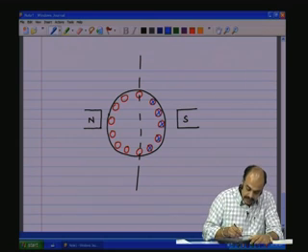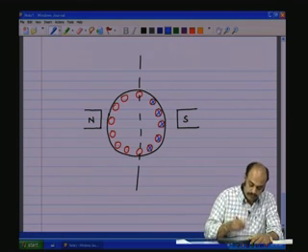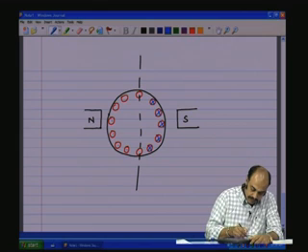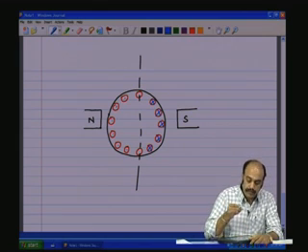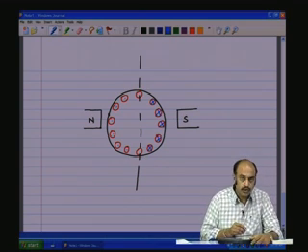So, again this conductor is going to have zero current because it is in the neutral zone, and then here the direction will be opposite, coming out of the board with varying magnitudes. The one nearest the north pole is going to have the largest magnitude of the induced current.